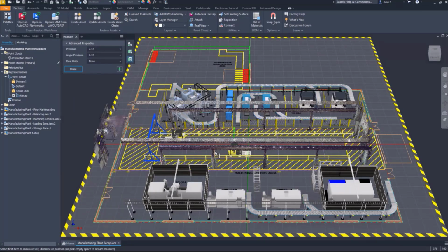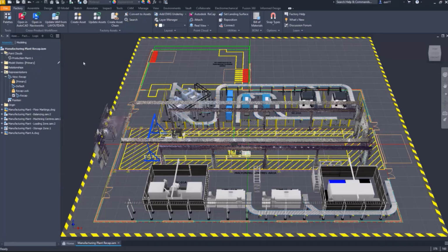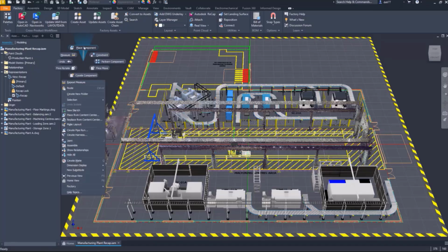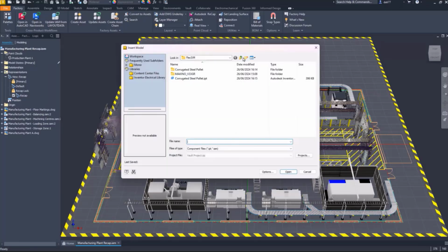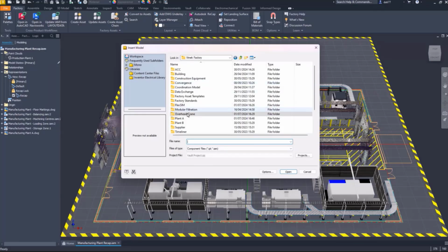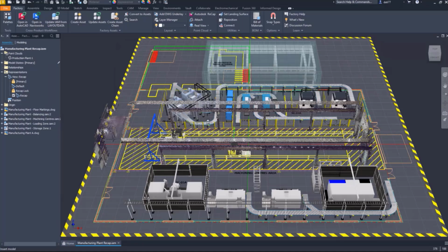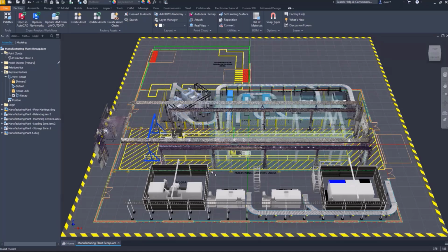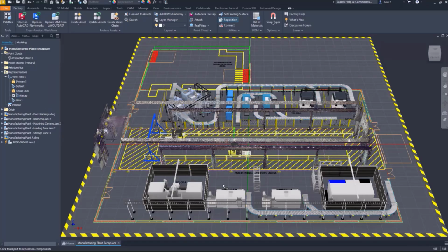The point cloud data also behaves like a 3D object where we can measure. We can use the point cloud data to measure from, let's say, pillar to pillar or pillar to the machines to check on clearance. Okay, this can be done. So you can reduce a lot of time if you request point cloud data or a 3D model from the client or from the factory.